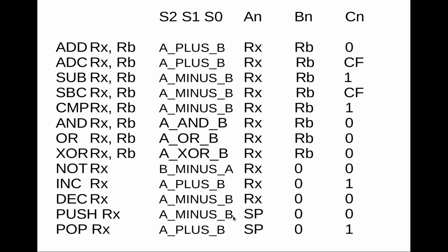And so in each one of these operations, the sequence is always the same. We need the ALU to perform some sort of calculation, and we do that by setting the ALU S0, S1, and S2 signals, as well as the ALU carry in signal and the ALU B signal to whether we want the B register or simply a hard-coded 0. And then this A input is always connected to the bus, so we also need to enable some register onto the bus. And so that is the first microcode cycle for any ALU operation.